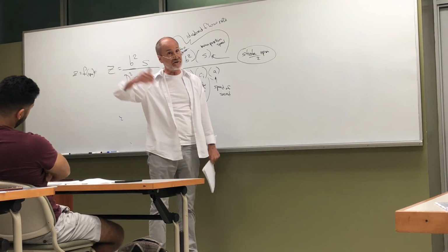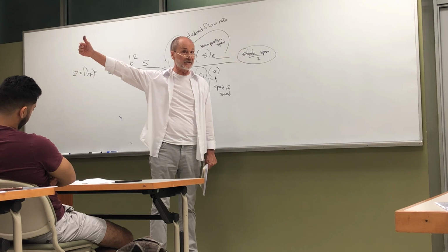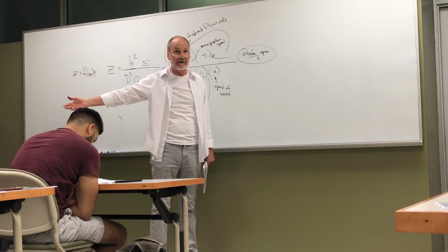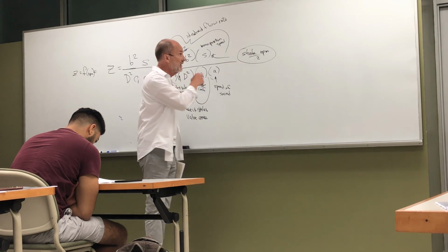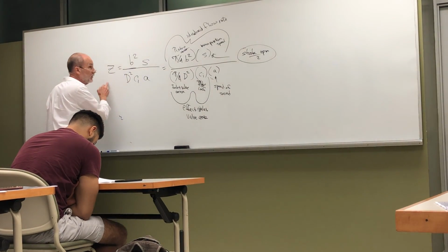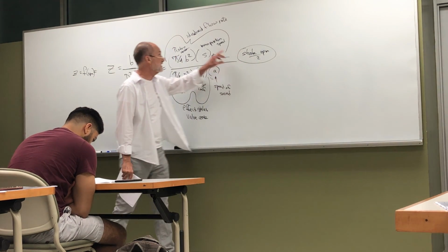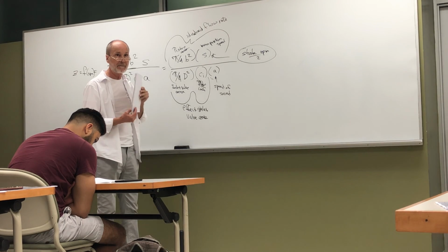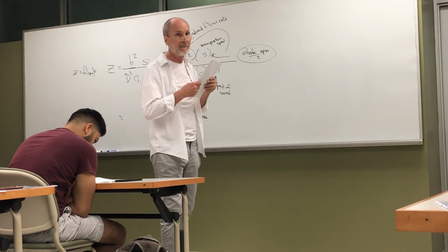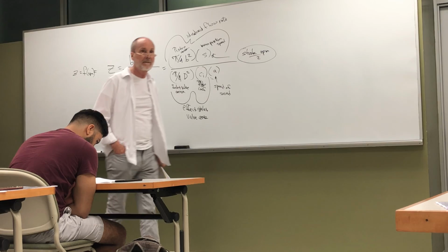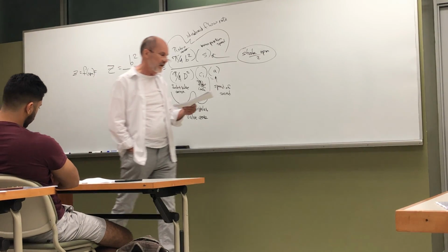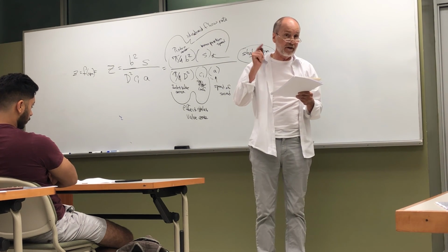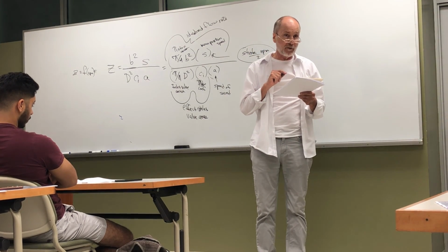As long as the engine will make a higher RPM, we can go to a higher Mach index number. We may not get any more power out of it. We're certainly not going to get any higher mass flow rate. But yeah, the Mach index number is only a function of RPM, and this is the idealized flow. Because you said that everything else goes constant at Mach index 1, why does the efficiency continue to go down then? Well, this one is the true volumetric efficiency divided by the volumetric efficiency at 0.5.